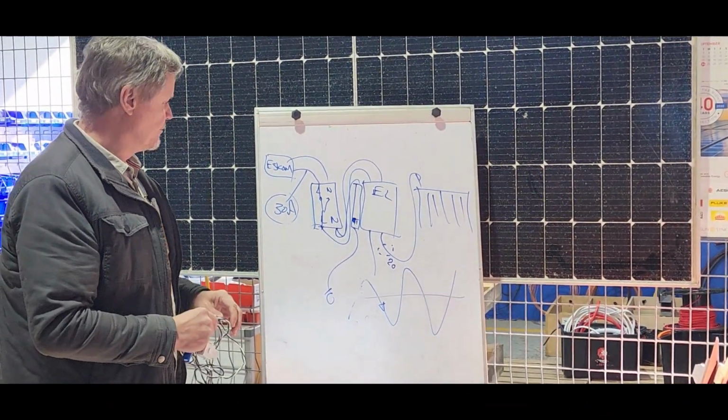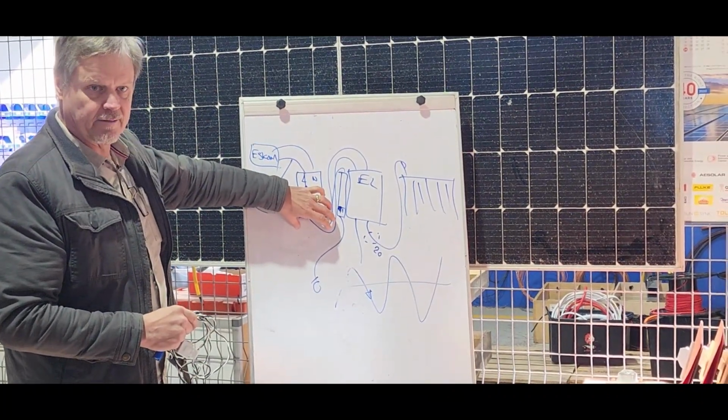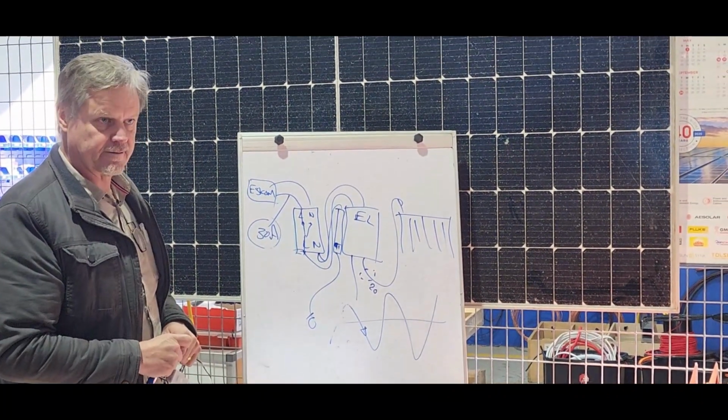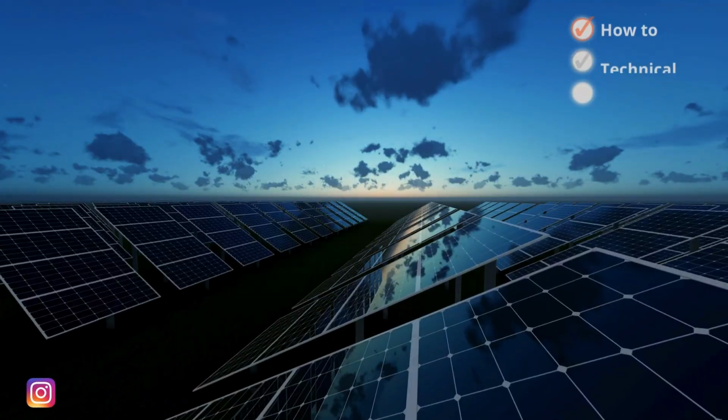So when you decide where to put the CT, normally just above or just below your main breaker. That's where the CT normally is. All right. Guys happy? Smart. Thank you.